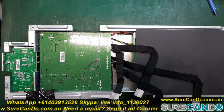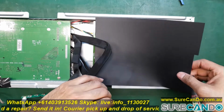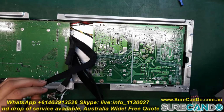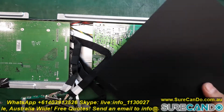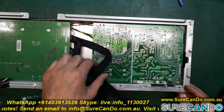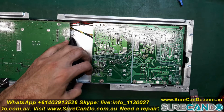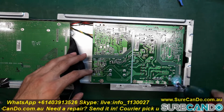So here is the baby. On the very left, the small controller is the USB adapter and controller, and this is the main power supply. And please make sure you haven't got the power cable plugged in while you're doing this. There is an on and off switch. Make sure it's in the off position, as you can actually kill yourself by touching the live circuitry around here. And also there are capacitors. The bottom pins are exposed here, so do not touch any of these areas.